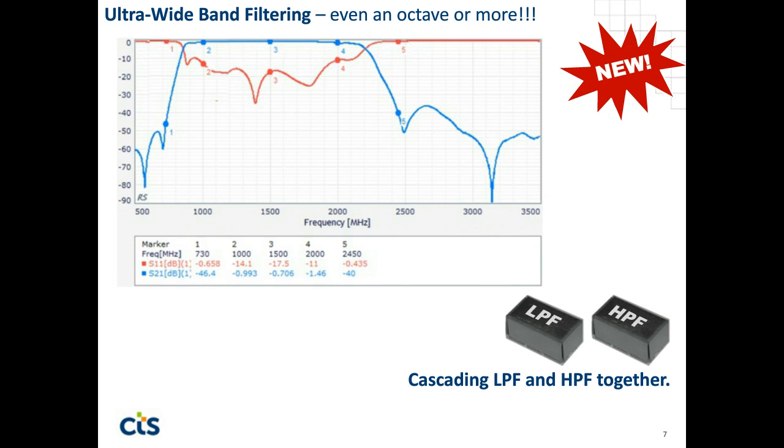They have very high Q and very strong rejection. So you end up getting an insertion loss from the low-pass filters alone of around 0.4 dB worst case. And they give close-in rejection all the way past the third harmonic of around 40 dB. So it's both strong rejection and low insertion loss and high power handling all in a single solution. That is the RLF family. It's the rooftop low pass filter family.